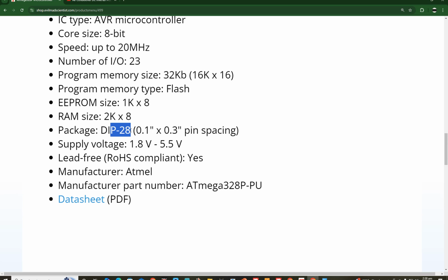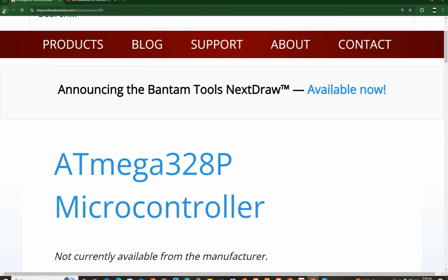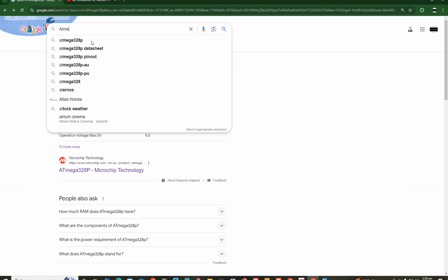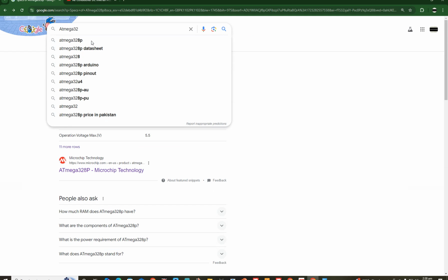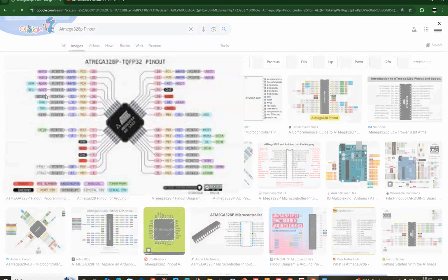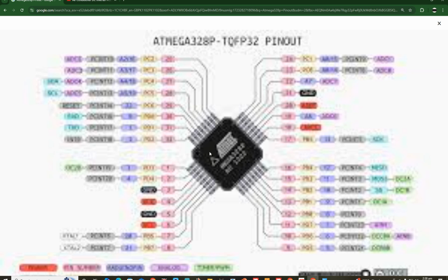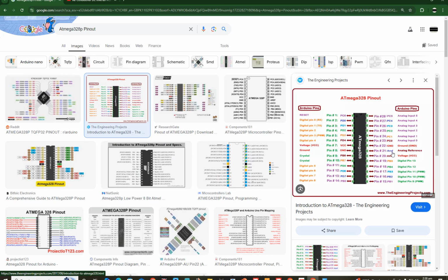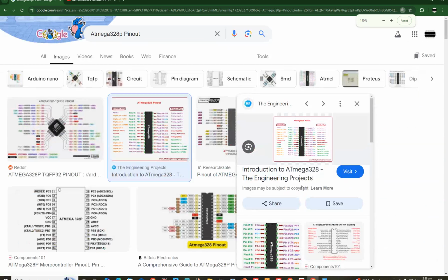It will allow you to see the architecture or the data sheet of this microcontroller. Let me show you the data sheet as well. Okay, ATmega328P pin layout, not the data sheet. Now see, this same microcontroller, this is the ATmega328 in the SMD package, having its ports etc. Now it's here in the DIP package. See, this is a DIP package of the same microcontroller.